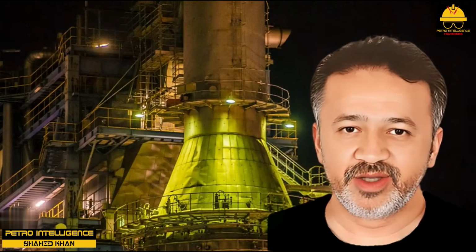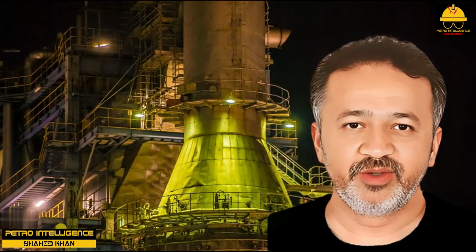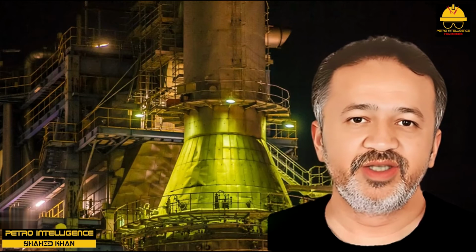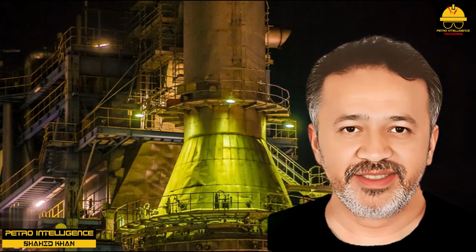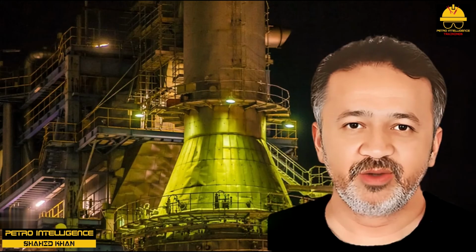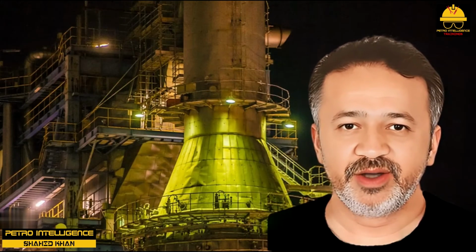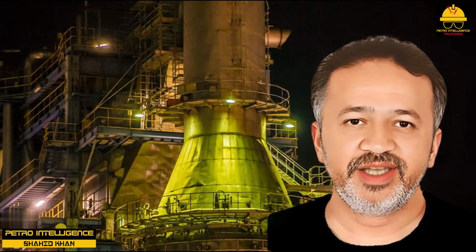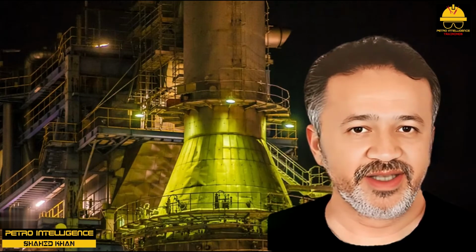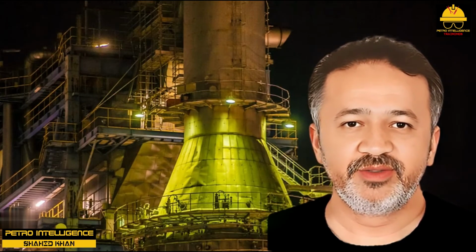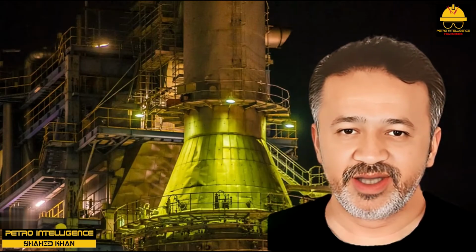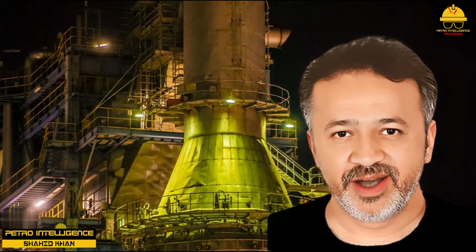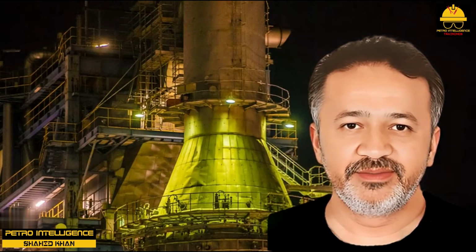The point of absolute combustion in terms of either maximum heater outlet temperature or minimum fuel fired for a given outlet temperature would correspond to the same flue gas oxygen content for a given furnace at the same moment in time. However, we must also note that this flue gas oxygen content that corresponded to the point of absolute combustion on, say, heater 3304A on Monday, January 2, 2023, at midday is not likely to correspond to the point of absolute combustion on the same heater on Tuesday, January 3, 2023, at midday, or even Tuesday, January 2, 1996, 1 hour or 1 minute after it was first determined.